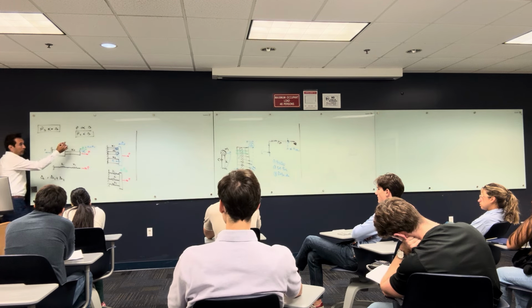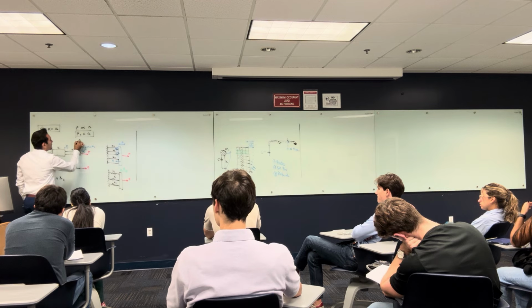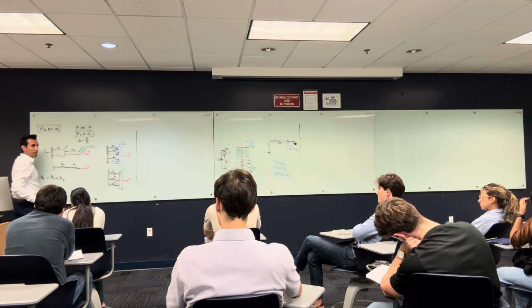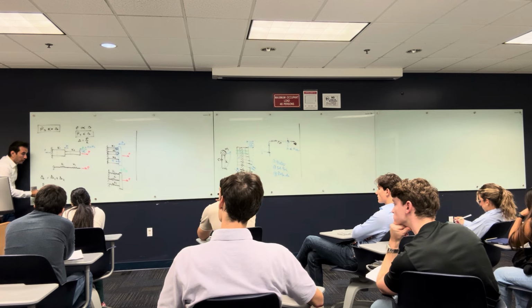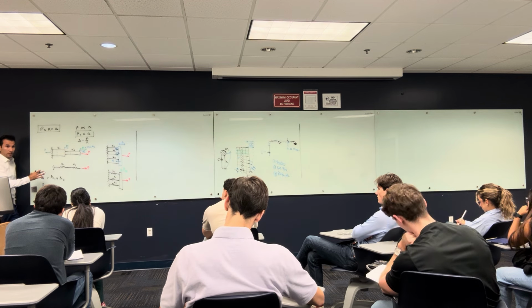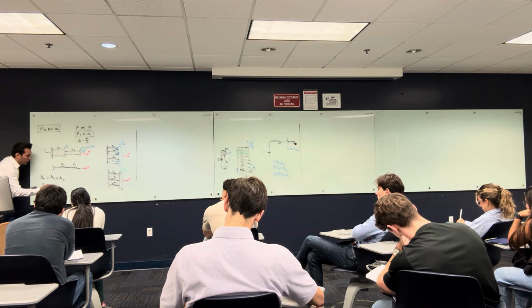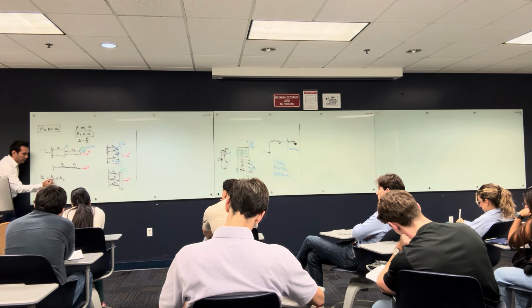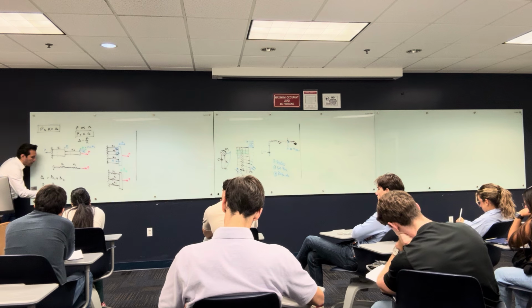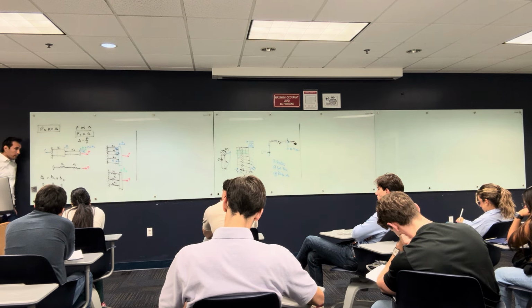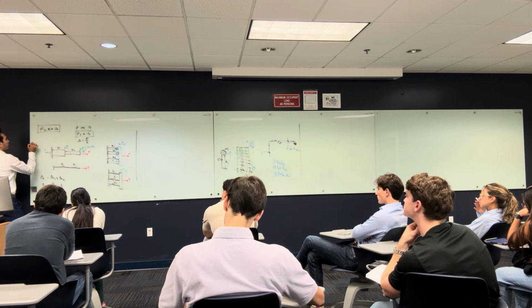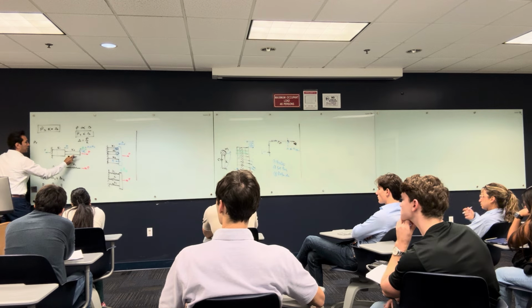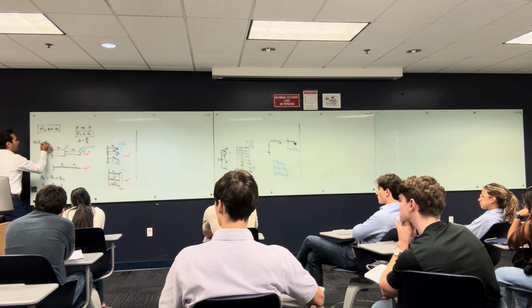If I want to find delta from this equation, delta is going to be B over K. So B over K, where K is the equivalent stiffness of the whole system, equals B1 over K1, because this is related to delta 1, plus B2 over K2. In this system, B is equal to B1 equal to B2.